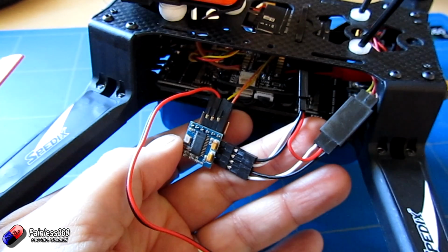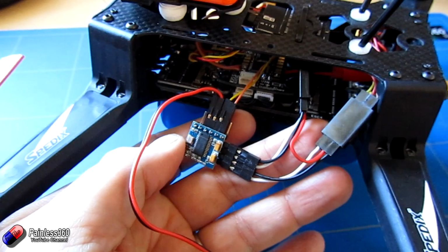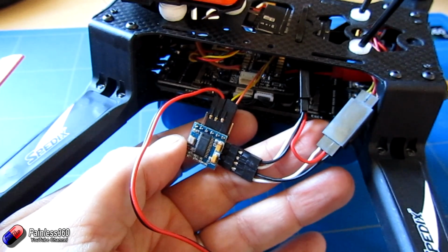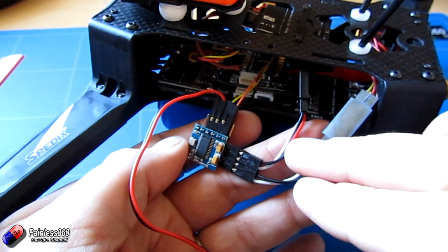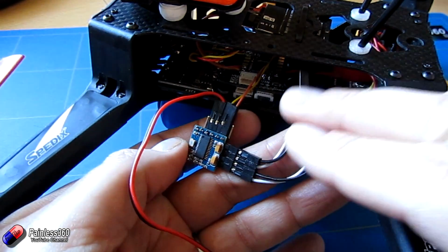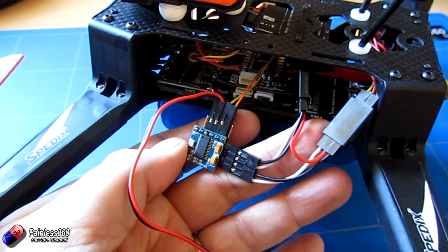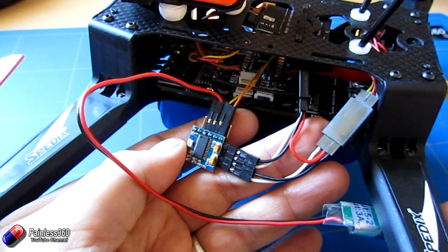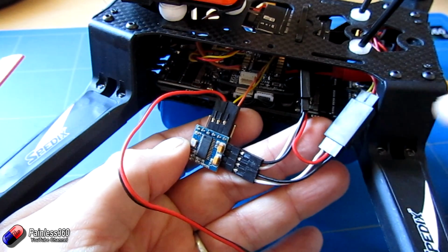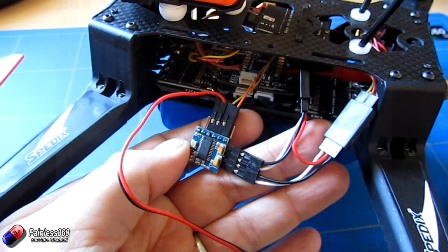Now I'm not going to keep the on-screen display on this KISS flight controller. I'm going to wait until the on-screen display is a little bit more sophisticated and a little bit more configurable, and then hopefully it'll be a little bit more useful for me. So once I've done this, I'm going to take it all off and connect the camera directly to the FPV transmitter. But now we've got this set up, we just need to plug this into the flight battery so that we get the 5 volts in, and then hopefully when we connect it all together, you'll be able to see an image that looks a little bit like this.